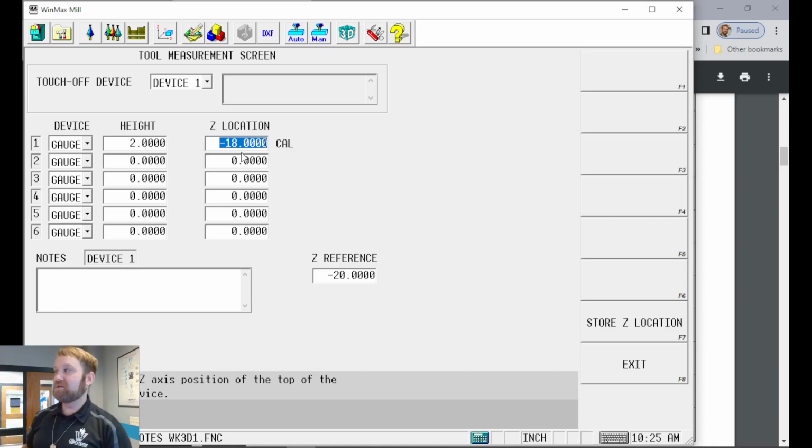Most of the time, if a tool doesn't store right, something's off in your calibration. Usually it's going to be an inch or two, because you're either using the wrong side of the block of the tool setter, or maybe somebody went in there and messed with the reference gauges. So I can visually look at that. When we get out to the machine, I'll show everybody how to do that. All right, I say that older controls don't have absolute values. Older controls don't, so you'll have to learn how to set them at the negative length.